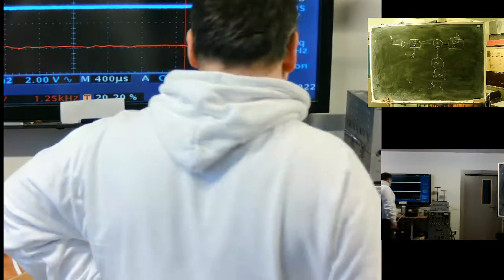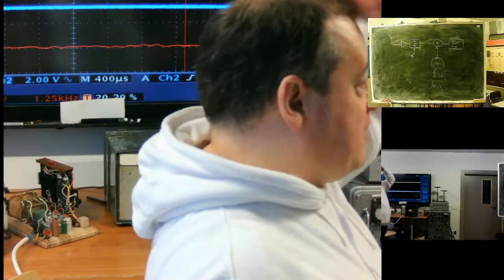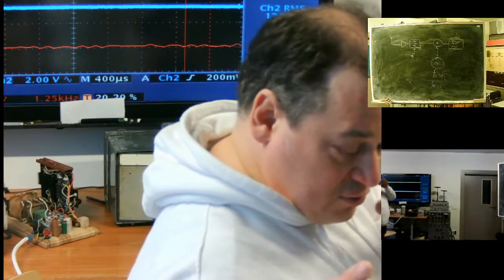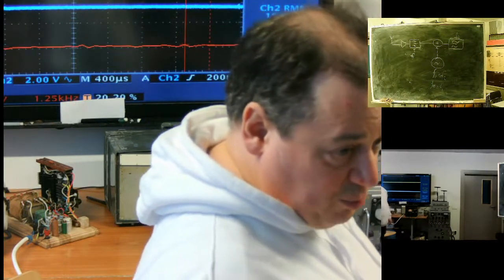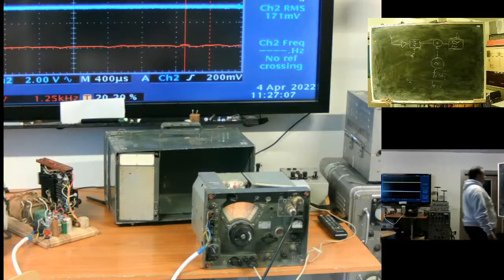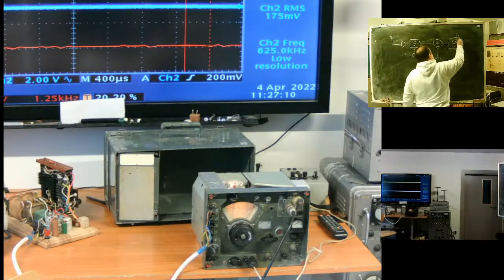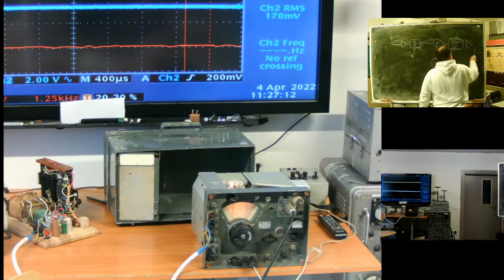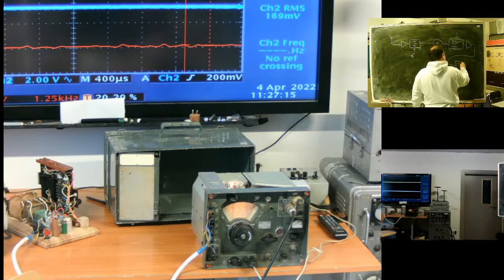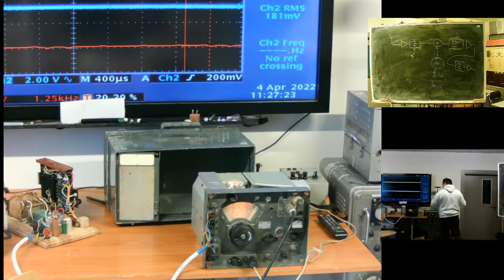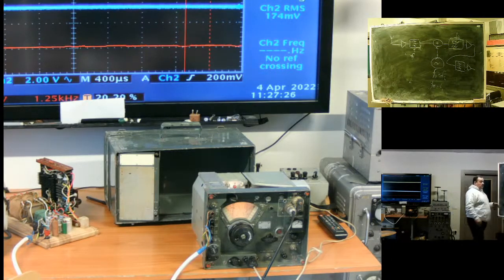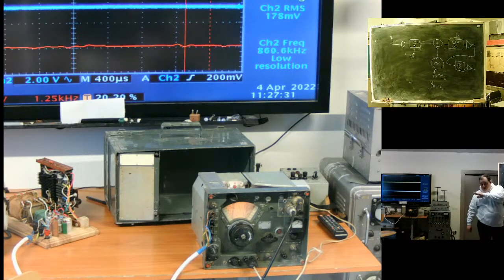The spectrum of the received signal is transferred to the processing frequency, and then processed with a series of filters and amplifiers, maybe more filters and more amplifiers. The spectrum is transferred with the help of the heterodyne to one frequency for all receiving frequencies.